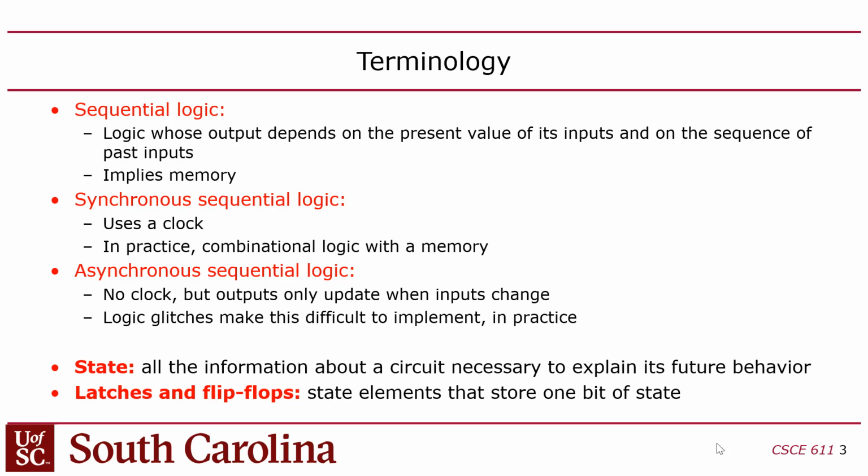And so there's some other terminology. Whenever I say state, you can think of state as basically the memory inside of a sequential logic circuit. But what it means is it's all the information required to explain future behavior. So when you design a sequential logic circuit that's not just a RAM or a register, the state is a concept that you have to incorporate into the design. And I'll talk more about that in just a minute. And then latches or flip-flops are what hold the state. Those are the memory elements that you'll use to hold the state.